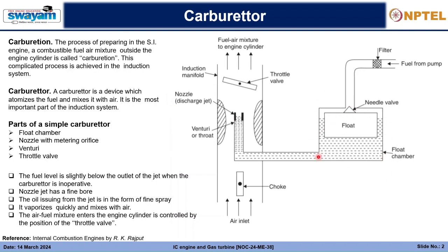This is the float chamber, and why is it called the float chamber? Because it has a float which is submerged in the level of oil out here, and has a needle valve which actually, if the oil content decreases beyond a certain point, then this float will come down, and this needle valve will come down, and the orifice will become open, and the fuel from the pump will be pumped inside the float chamber, and accordingly this chamber will supply the fuel into this throat of a venturi,